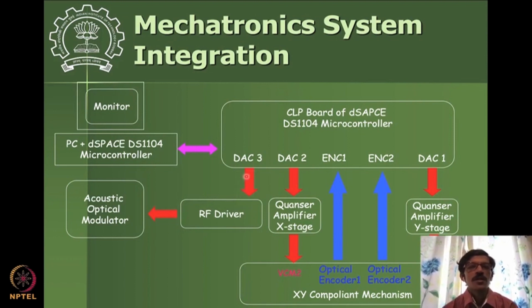Depending upon this analog voltage, your laser intensity will be controlled. This is the system you need for operating the laser on and off depending upon XY position, so that your scan gets done in the manner that you would like.